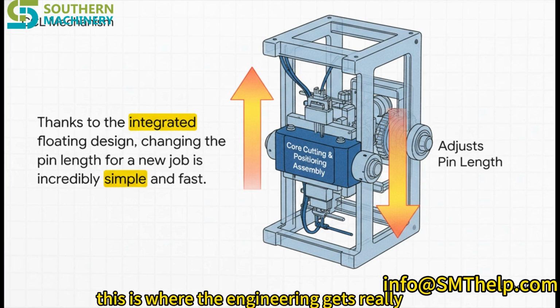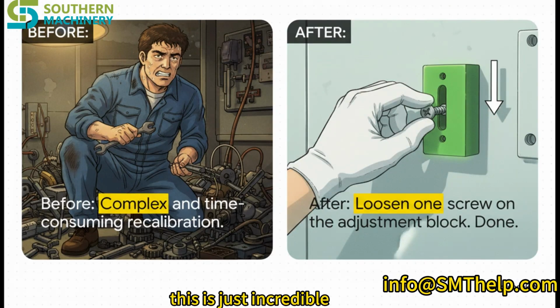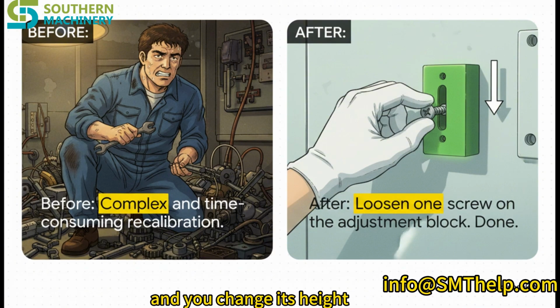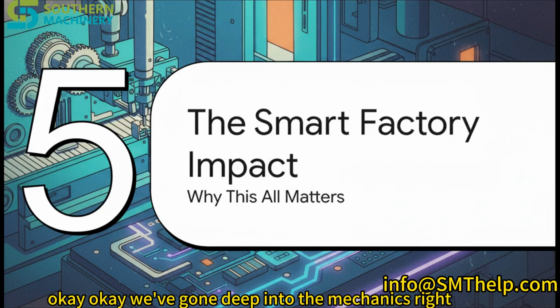This is where the engineering gets really, really elegant. The entire CCL mechanism uses what's called an integrated floating design. This is just incredible. On older, clunkier machines, changing the pin length might mean a whole complex recalibration process. But here, you just loosen a single screw on this little green block and you change its height. That is it. It is so simple, it's so fast, and it means you have almost zero downtime when you're switching between different jobs.